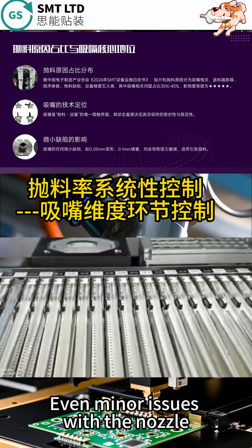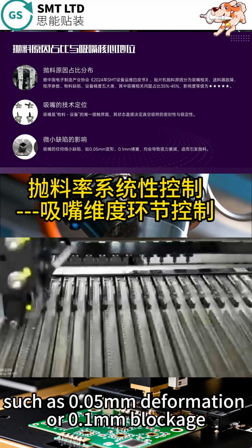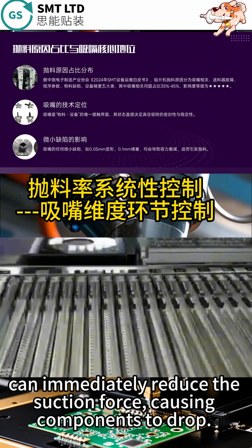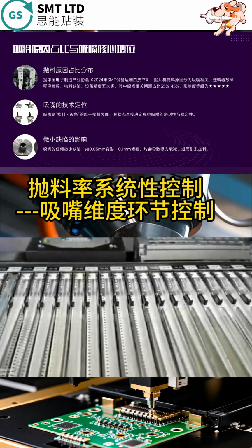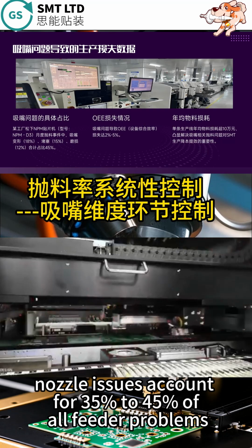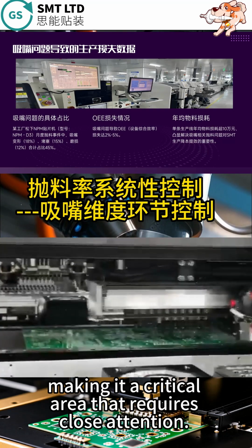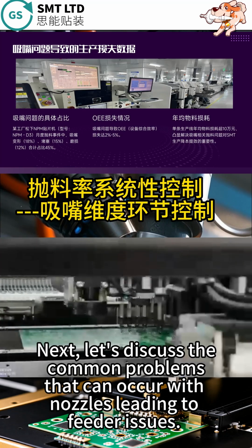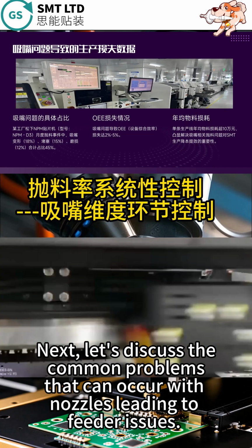Even minor issues with the nozzle, such as 0.05 mm deformation or 1 mm blockage, can immediately reduce the suction force, causing components to drop. According to industry-wide papers, nozzle issues account for 35% to 45% of all failure problems, making it a critical area that requires close attention. Next, let's discuss the common problems that can occur with nozzles leading to failure issues.